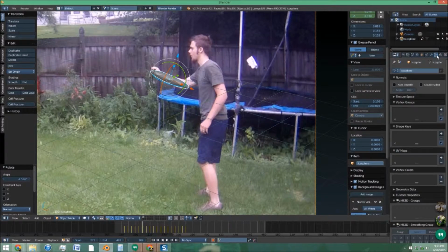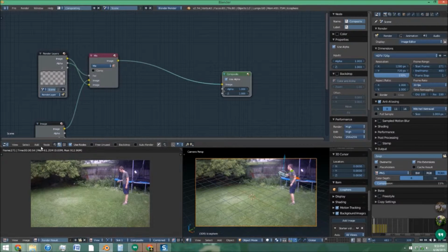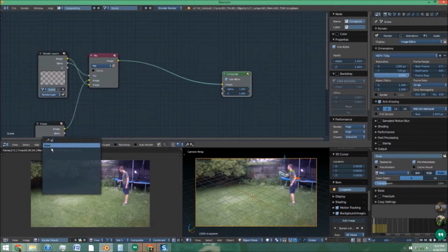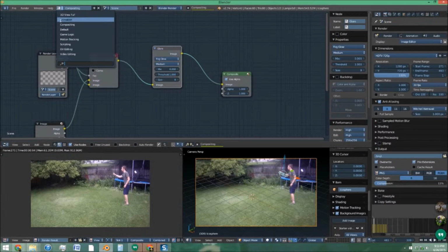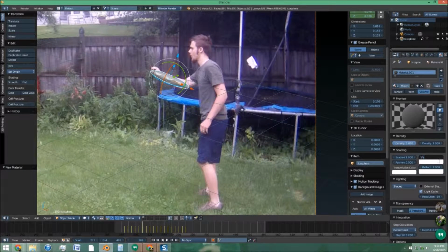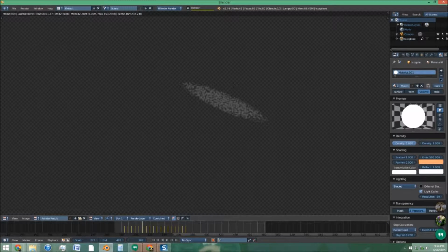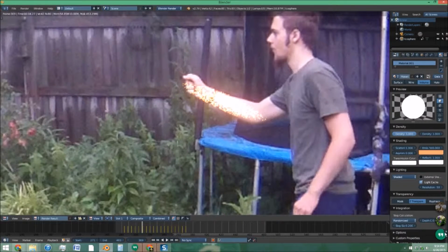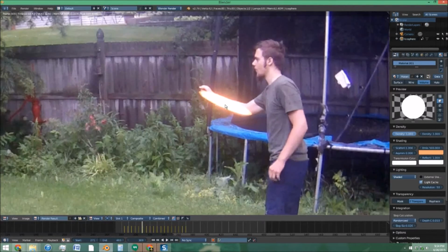Alright, so we next set up our material, and also one thing I forgot to mention before, over in the node editor, we're going to add a layer node. Set it to fog glow, size 9, leave everything else default. Add new material, volume, set emission to 500. I know it's a bit heavy, but rendering transparent backgrounds and volumes gets a little odd. Oh, and also set step calculation to 0, so it's smooth and actually renders in well.